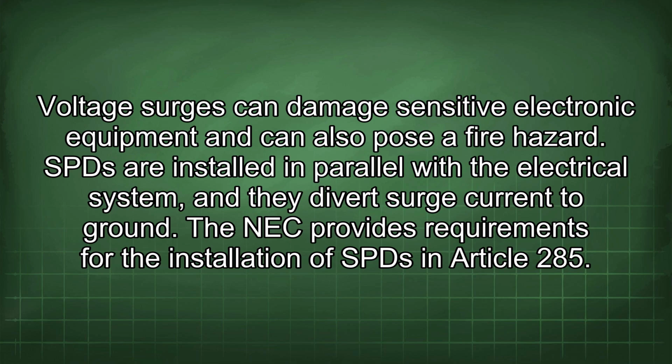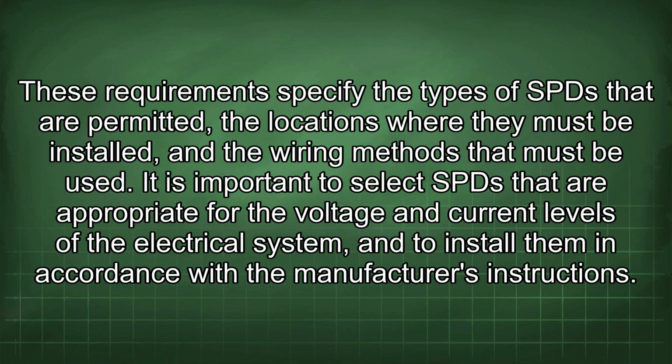The NEC provides requirements for the installation of SPDs in Article 285. These requirements specify the types of SPDs that are permitted, the locations where they must be installed, and the wiring methods that must be used. It is important to select SPDs that are appropriate for the voltage and current levels of the electrical system and to install them in accordance with the manufacturer's instructions.